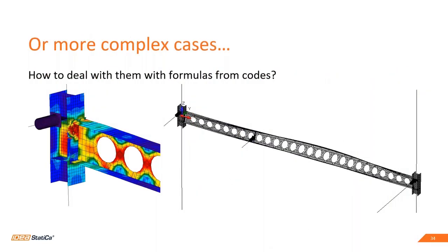And of course, you can use this application on more complicated cases. For example, this is a castellated beam with circular openings. There are some cleat connections, and you can see that the bracing, which is located at approximately 1/3 of the span, has a big influence on the eigenshape.